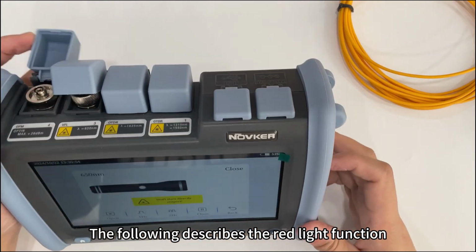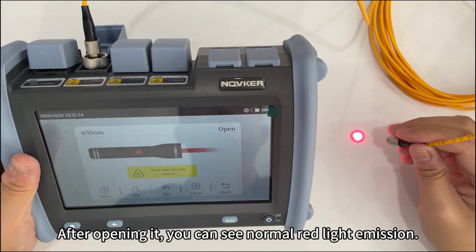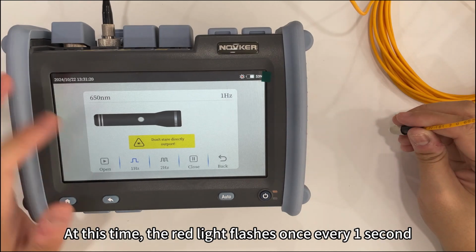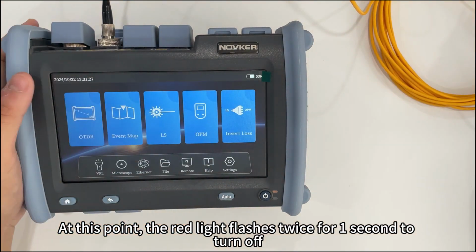The following describes the red light function. Plug the fiber into our red light interface. After opening it, you can see normal red light emission. Switching frequency, the red light flashes once every 1 second. Switch to 2 Hz, and the red light flashes twice per second.